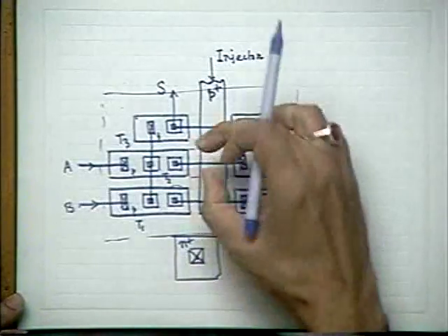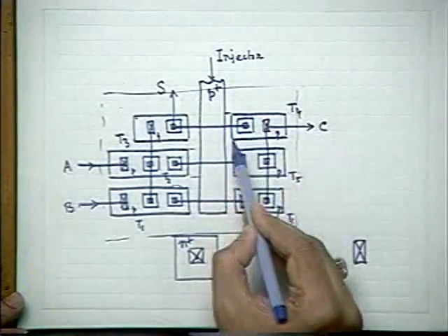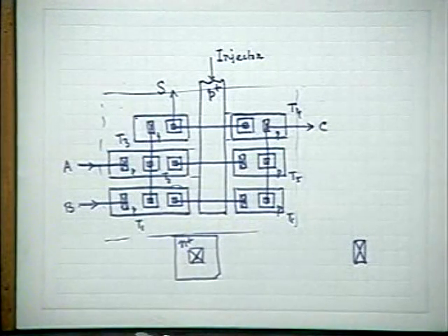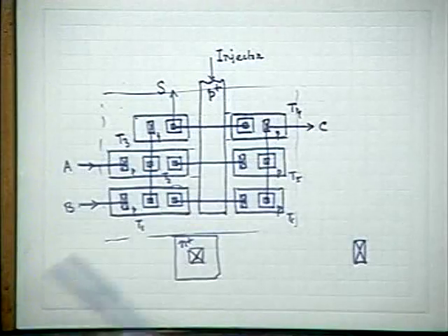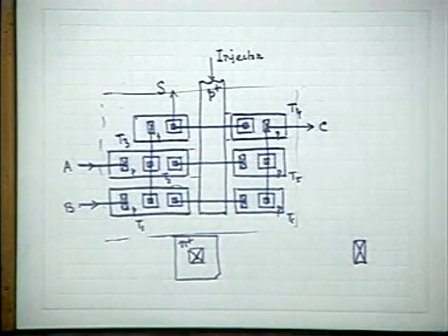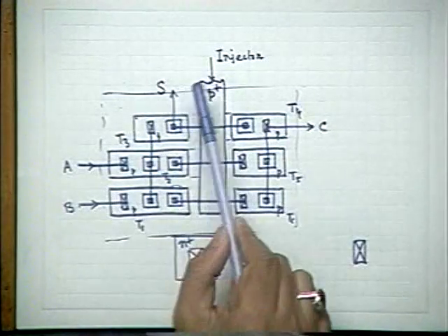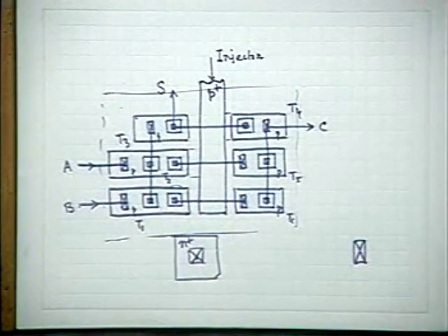Another thing you have seen, that this distance has been kept the same. This width of the base has been kept the same for all the transistors. Similarly, the separation between the injector and the bases has also been kept the same. What does it signify? The width of each base and the separation. So they supply the same I injector to all the bases. What is the total current supplied? It is 6 times I injector. The actual total injector current is 6 times I injector, individually supplied to individual transistors. This has to be remembered. So with this, I think today's time is over.